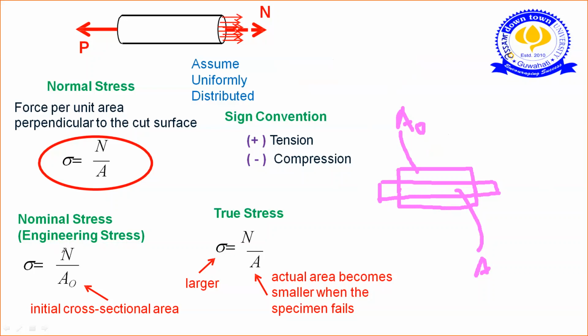You will take that area, and for this formula, you get nominal stress. And this stress is used in your engineering problems. All the numericals we will get in this class, we take normally for structures this nominal stress. But sometimes they may ask you what will be the true stress.